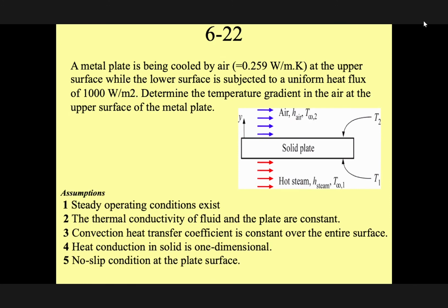Therefore, look at here. Every time we would like to solve a problem, we have to put the boundary. Our solution is only valid for such scenario. We assume a steady state condition. The thermal conductivity of the plate is constant. It's not a function of the temperature. Convective transfer is constant because we are assuming it's a steady state scenario. And heat transfer is only one dimensional.